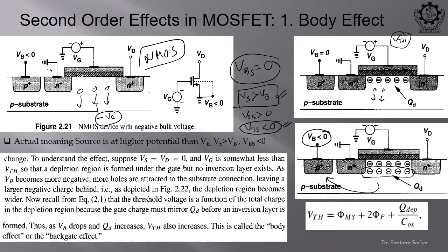Clear? So, in case 1, if you need to invert this, if you recall our VTH expression, that threshold voltage depends on our total depletion charge, is not it? So, if you want to add more positive charge on this gate terminal and this is balanced, then what will happen? If we increase a little bit more, then electrons will come out of this junction, right.